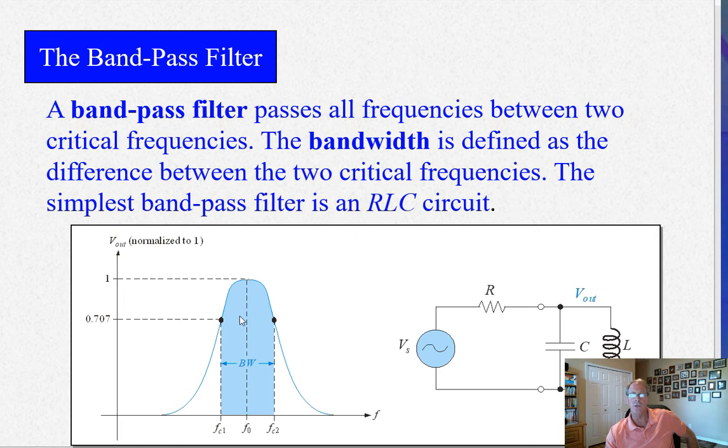On either side, if you go lower in frequency, what happens to these parts, the capacitor and inductor? Well, at a low frequency, the inductor is what? That's a short circuit. It's just wire, right? Whereas at high frequency, that coil of wire generates a magnetic field. It doesn't want to let that high frequency through because it has to build up the magnetic field and collapse it, and it won't allow you to do that very quickly. So it becomes an open circuit at high frequency.